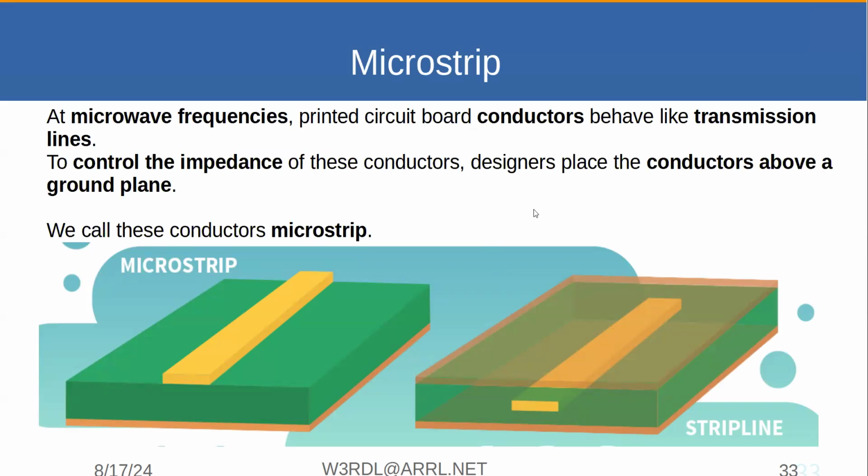And microstrip. This is another thing with dealing with dielectric. For high frequency, like UHF things, when they're doing circuit board layouts, they'll actually create little transmission lines so they can control the phase shift of signals.